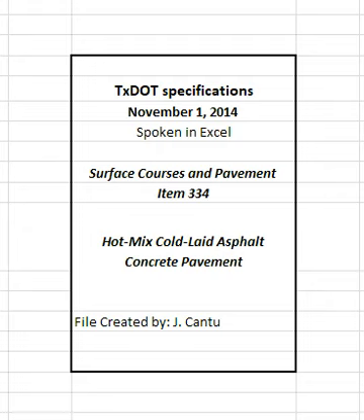4.2.1 Stockpiling of aggregates. Provide a smooth and well-drained area, cleared of trash, weeds, and grass. Build stockpiles in a manner that will minimize aggregate degradation and segregation. Avoid contamination and mixing of stockpiles. Provide aggregate stockpiles for a minimum of 2 days production before beginning plant operations.